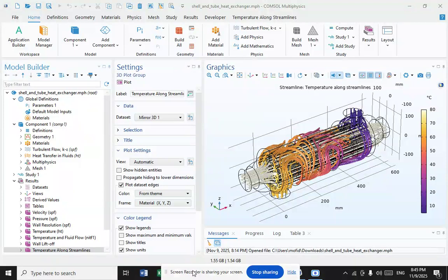Pillow plate heat exchanger. A pillow plate heat exchanger is commonly used in the dairy industry for cooling milk in large direct expansion stainless steel bulk tanks. Nearly the entire surface area of a tank can be integrated with this heat exchanger without gaps that would happen between pipes welded to the exterior of the tank. Pillow plates can also be constructed as flat plates that are stacked inside a tank. The relatively flat surface of the plates allows easy cleaning, especially in sterile applications.